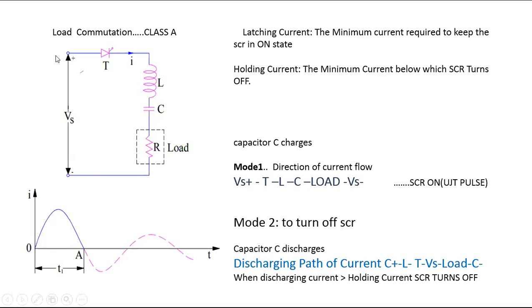But in practice, how do we explain the direction of current flow? Whenever any circuit is turned on, the direction of the current starts from the positive terminal, and from the positive terminal to which component do we have? SCR. So current flows through the SCR. Then only junctions J1 and J2 are forward biased, but we must immediately apply a pulse signal to the gate terminal. Then immediately all three junctions are forward biased. Now SCR is on. When SCR is on, it can control any object. Now the direction of current flows from where to where?